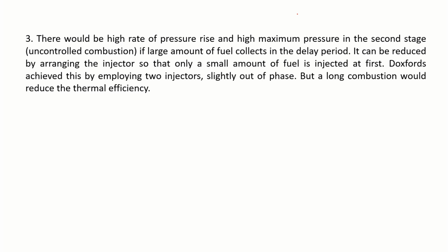In a petrol engine, the ignition limits are approximately 10:1 to 20:1, and most of the time the petrol engine runs on the richer side. So I can call the correct air fuel ratio around 14.7:1. In a diesel engine, the beauty is, even though the air fuel ratio is 14.7:1, most of the time it runs on the leaner side, that is 20:1 to 100:1. That's the beauty of this.